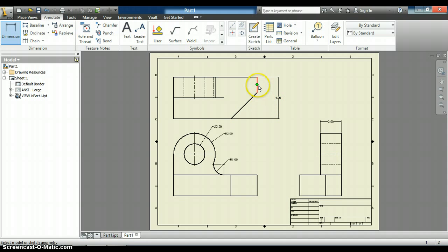So next, as I said, we need to do this dimension here. Again, we can't really do it here very well because we have all these lines in the way. It wouldn't look very good. So in this case we can simply click on this line and drag outward. Since this is probably going to be the smallest dimension on this view, we want to keep this closer to our object instead of farther away. So right about there would probably work for now. We may have to edit the 4 dimension later on. That would be the 4.